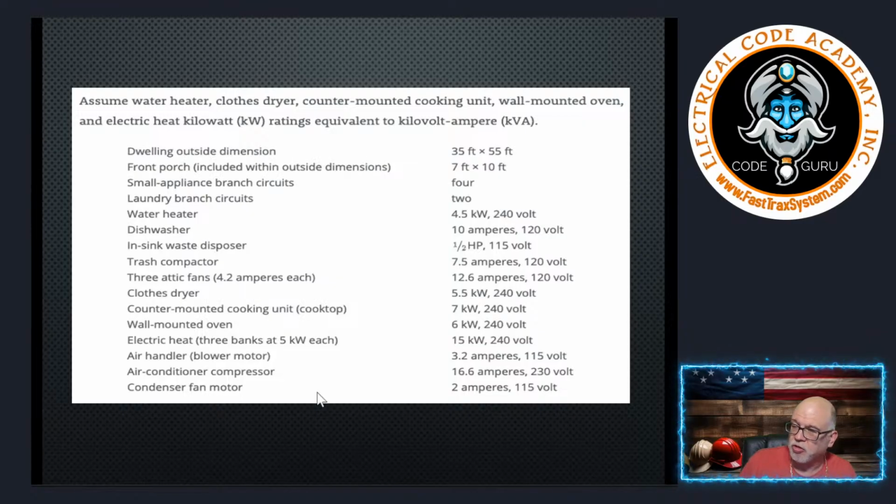All right? So it's only the 240 volt loads, except for the range and the dryer, which obviously you electricians are familiar with that, right? We're going to run 4 conductors to those, and they have some elements in there that are going to need 120 volts, right? So definitely we're going to have some neutral loads associated with the dryers and the ranges. So we will take care of that as we move through it. But just so you know up front, they're going to be at 70%. And we get that allowance in 220.61b. So anyway, we'll kind of work through those type of things.